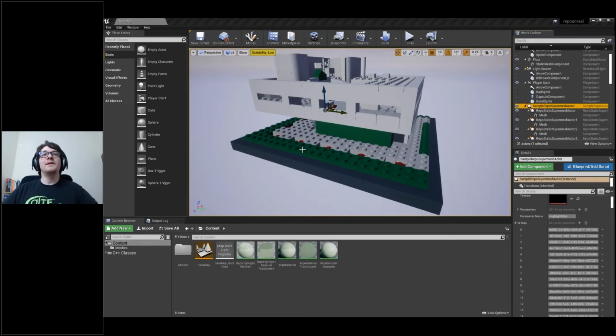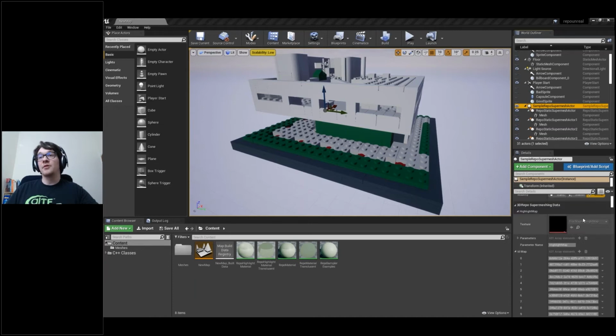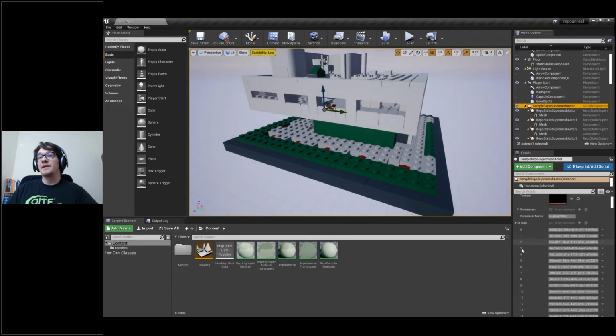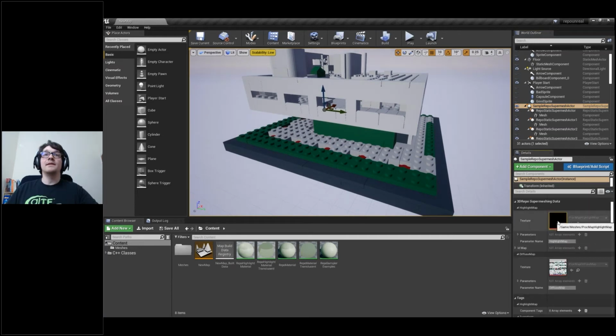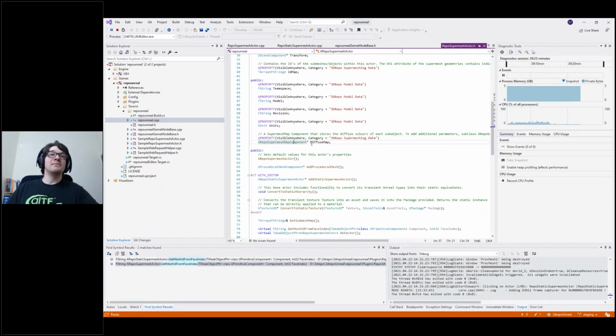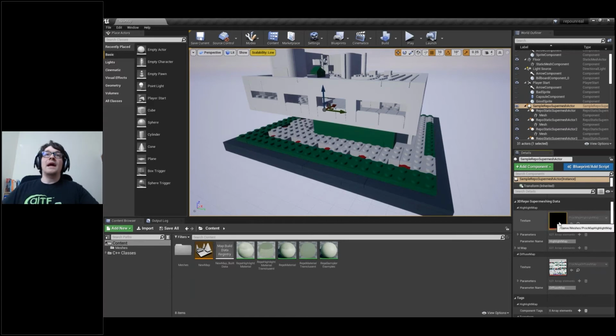The second level up is the metadata that's stored locally. So on this actor here, this would be things like the diffuse color and the highlighting state of a particular object. These exist on the actor and they are managed by URepo supermesh map components. These are actor components, and what they do is manage these texture maps and provide a nice API for you to set and clear properties based on the mesh IDs, and then also update any materials as appropriate on the actor. The fact that they are textures is an implementation detail, but it's important because it means that those can also be queried in these materials.